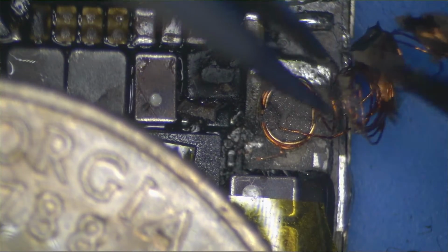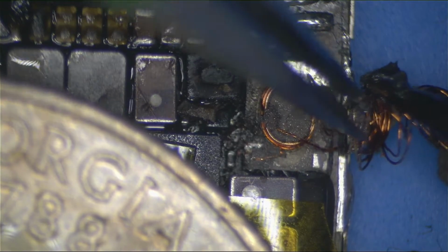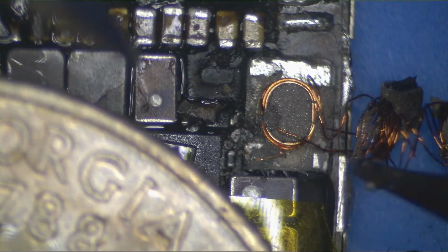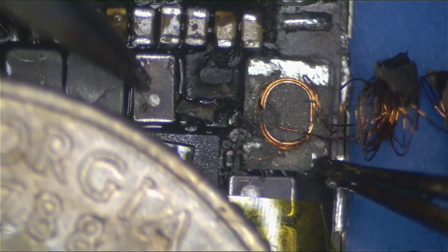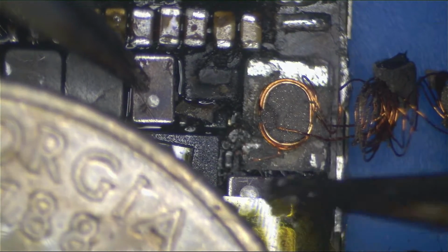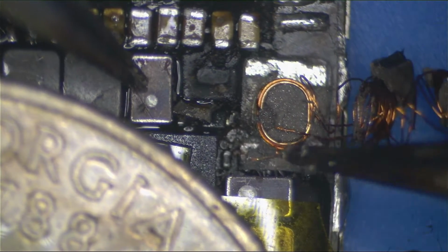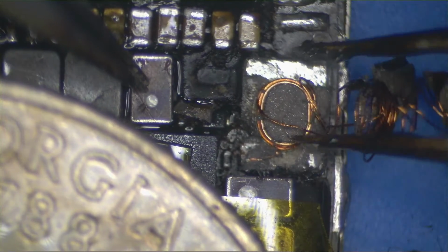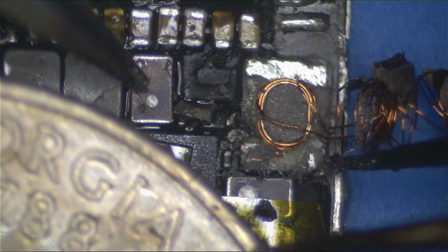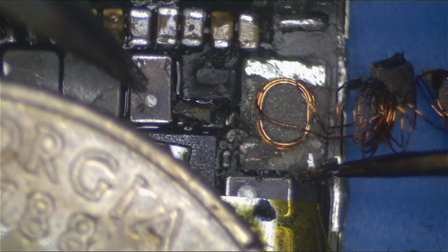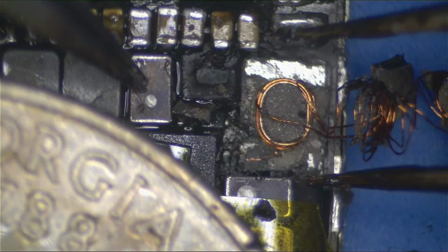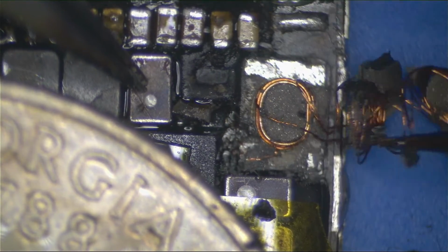Now that I have the top pad exposed, you can actually see here those windings, how they're kind of silver there. That actually might be where they shorted together. The coating on the wire makes it turn that color of brownish copper, but there's some silver on the right there, which indicates to me that that might be where it's shorted, which is kind of cool. I've never actually seen that before, but that's the idea of how the coil fails, is that the windings internally short together.